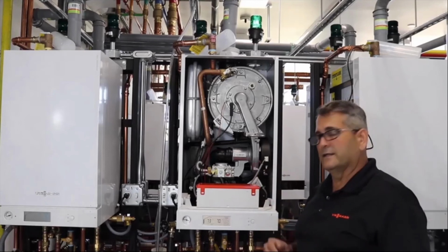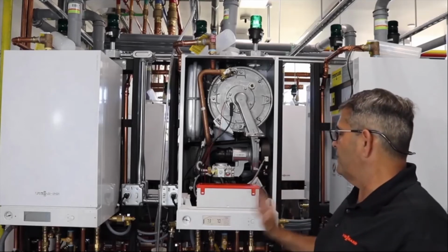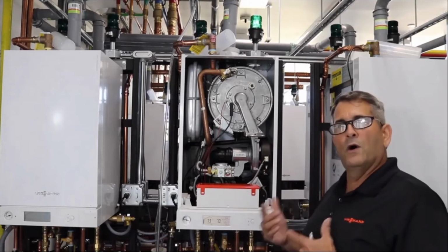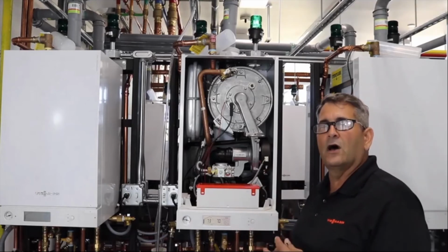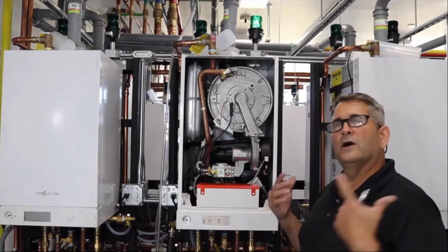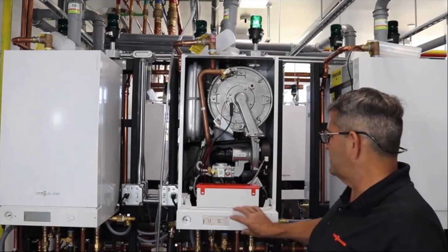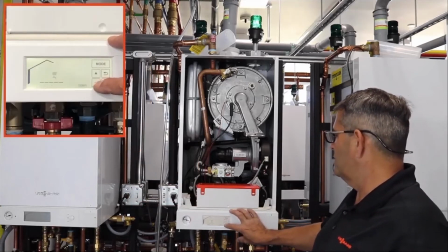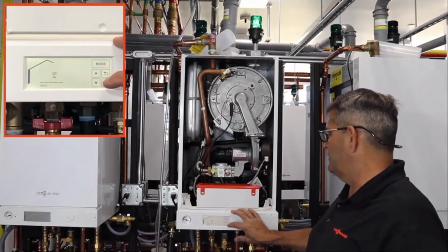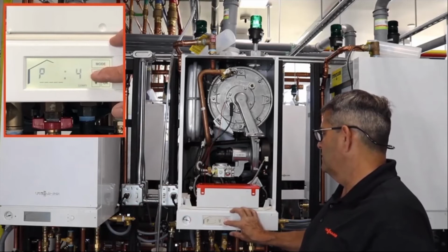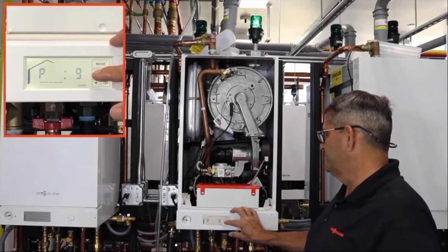But like I said earlier, if you do not see a fault on here when you get there because the homeowner happens to push the reset button, go watch our video on how to access our fault codes on this boiler and how to clear them. So before we leave any of our jobs, you guys want to check that. We'll hit the mode button and go to configuration or config on this boiler. Hit OK. I'm going to put 10 here.